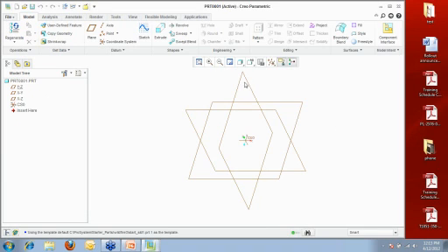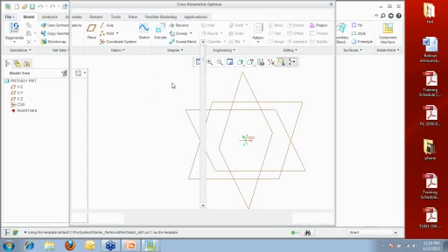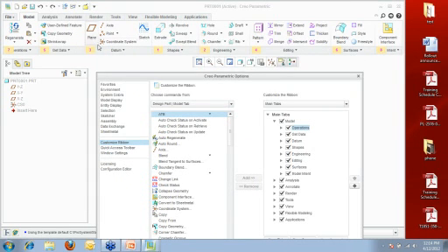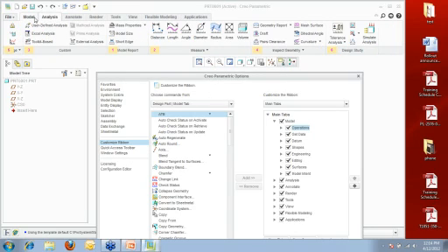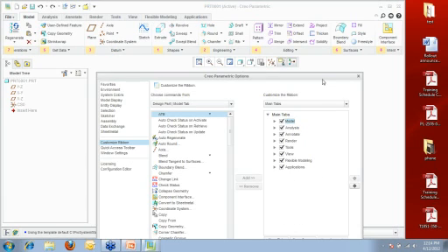Now, a little bit of a tidbit about the interface. If you haven't seen some of our other webcasts, we always start out with the differences in the interface for Creo Parametric. PTC now has the ribbon interface, and what really makes it unique is that I can right-click up in the interface and do a customize the ribbon. What I get is an interface that allows me to not only drag areas around, but also turn tabs off and on just by picking and clicking. And on top of that, I also have the ability to create new tabs.